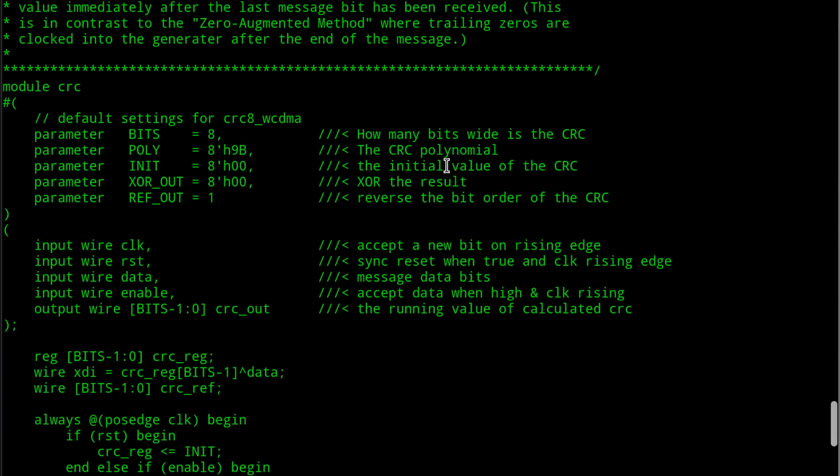You see these used a lot in serial data communication, where a lightning strike can create some static noise while bits are being transmitted. And they may be flipped in a small group, while all the others that came before and after are probably okay. That's also true on disk surfaces. Any magnetic medium has that nature. And a CRC works well for that, provided that your polynomial length is big enough to span whatever the total number of bits in a row might be corrupted, so that you can detect that error.